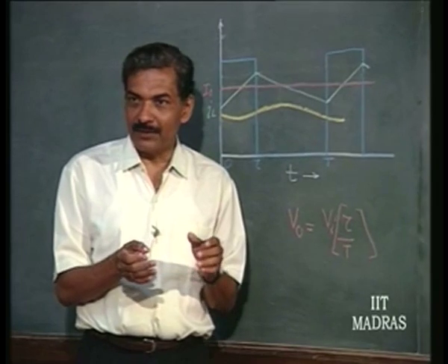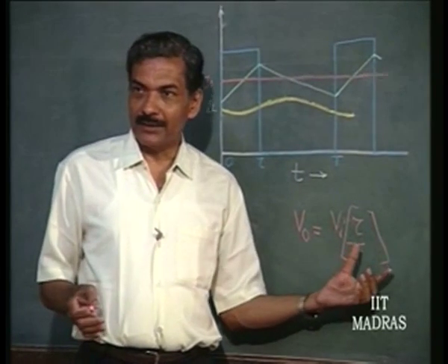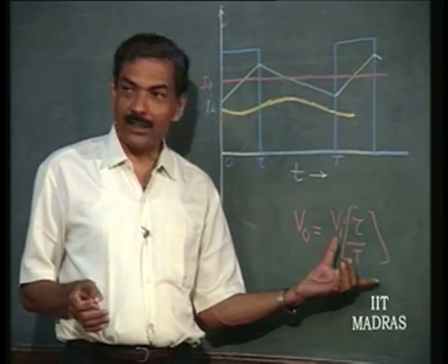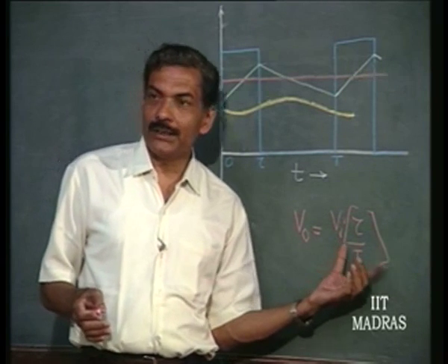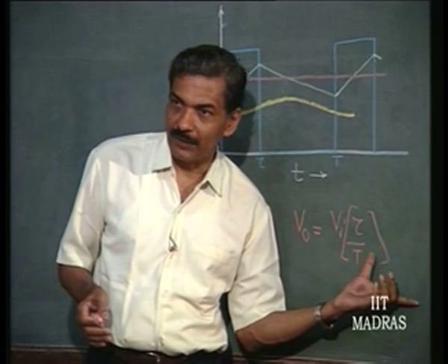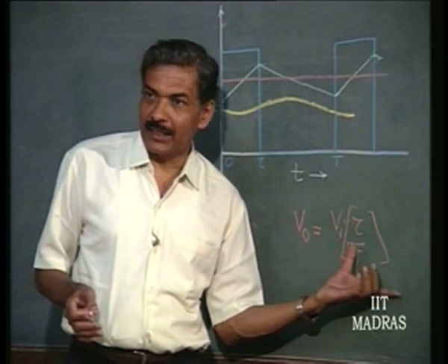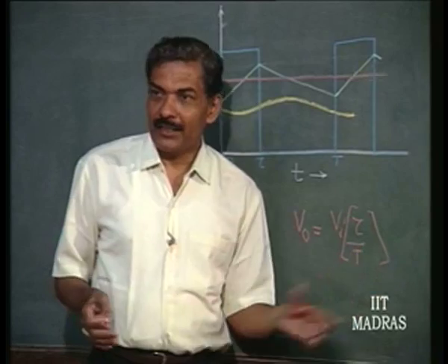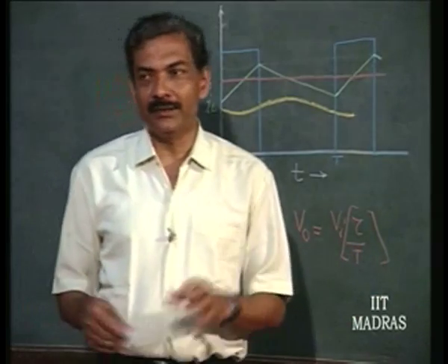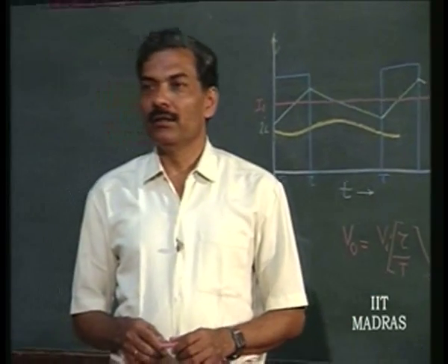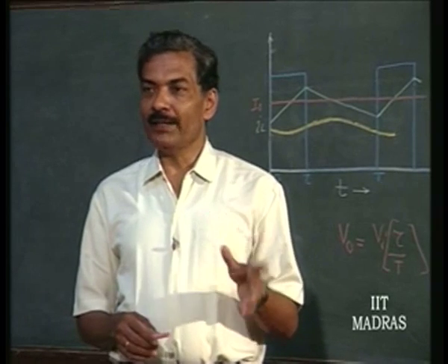This difference is now going to control the duty cycle. So, it is a voltage controlled duty cycle generator that is required for this, a DC voltage controlled duty cycle generator. In communication terminology, this circuit is called pulse width modulator.